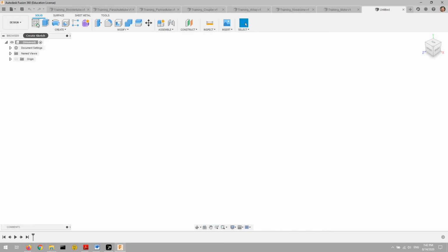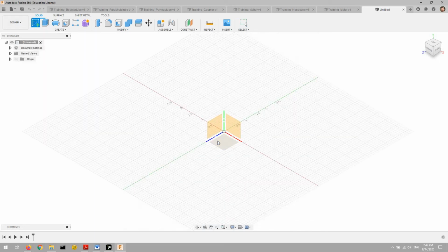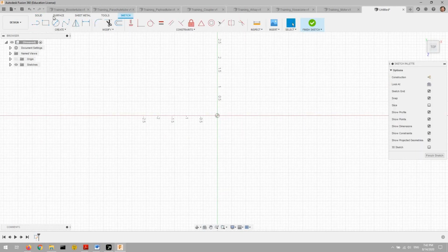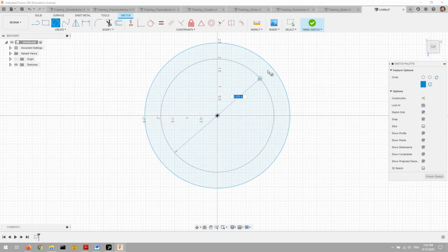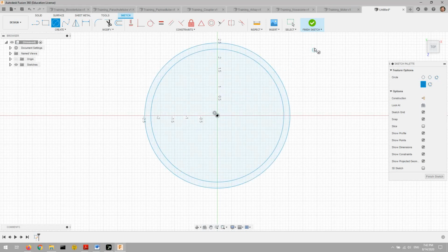And for our next trick, we're going to make the enclosure for that motor. So it, just like many other things in this design, is a hollow tube that's going to be the same height as the motor, but the inner diameter is going to be the diameter of the motor, and the outer diameter is going to be that plus 0.17 inches.